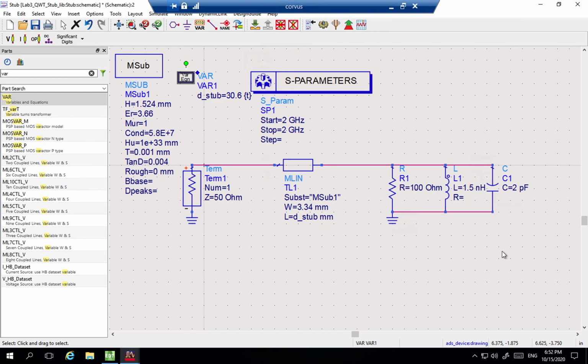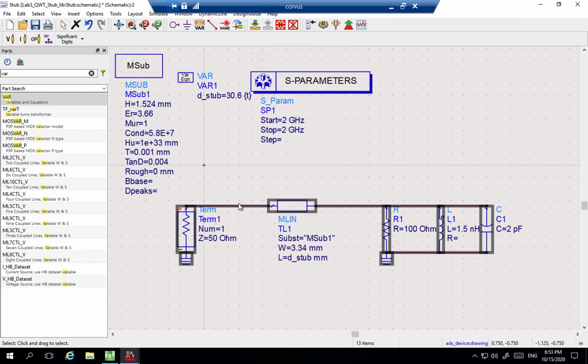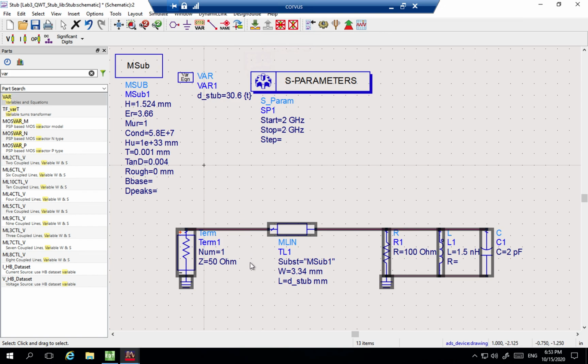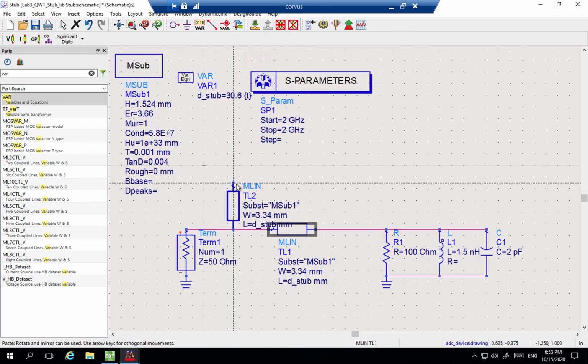Now the next part, part F, is to add another microstrip line for the short-circuited stub, which has a certain length, which we don't know yet, to achieve yn2 equals zn2 equals 1. In simple words, what length of stub do we need in order to bring that dot on the Smith chart to the center of the Smith chart? That's what we're trying to answer now. So we can simply add another microstrip line block, just a shunt in parallel, and we want it to be short-circuited, so we'll add a ground for that. You can just copy that here. Control R to rotate it, and then we can add a ground.